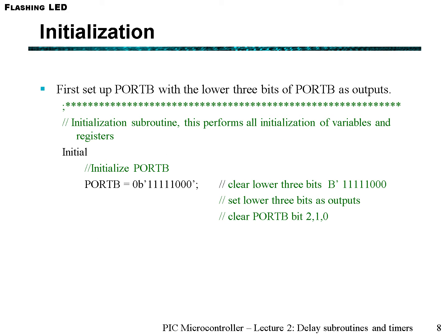So let's start looking at the initialization. So firstly, we know in our example we're using port B to put our LED outputs, and specifically the lower 3 bits of our port B as outputs. So first we need to clear the port B bits, so we can initialize them as specifically the last 3 bits as 000, and then there's one other step that we need to do, and I'll leave that as an exercise for you to do.